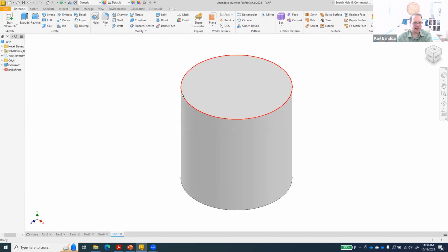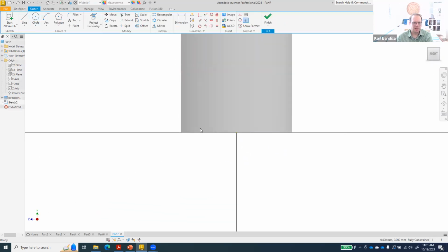To do that, we'll have to have a sketch plane that is right out here. In our case, because we put it right there, either of our orange origin ones is going to work. So we can sketch onto there. And let's start down here. So we can do something that catches that edge line there. And let's do these at maybe 60 degrees. And let's do 3. And then do another one that is 3 and 60.